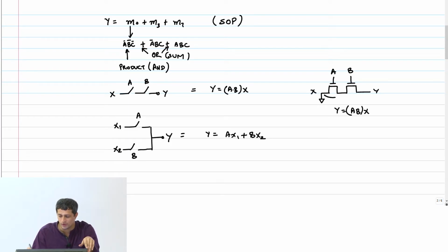The zero from here will appear here, and that zero will also percolate to the output Y. No problem. On the other hand, if I connect this to VDD, then what will go through from here to here is VDD minus VT, and further from here to here is also VDD minus VT, right? Whereas for 0, it goes to ground, right?